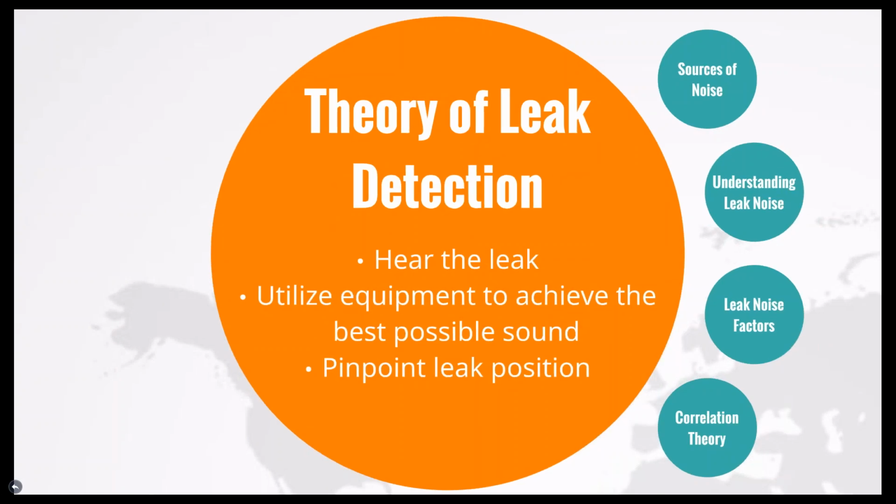The next step, the theory of leak detection: hearing the leak, utilizing equipment to achieve the best sound possible, and pinpointing the leak position. Because of pipe material, pressure in the pipe, and backfill around the pipe, the noise that a leak creates can vary from one pipe to another, which is the reason I think a lot of cities are challenged to get staff to focus on a leak detection program.